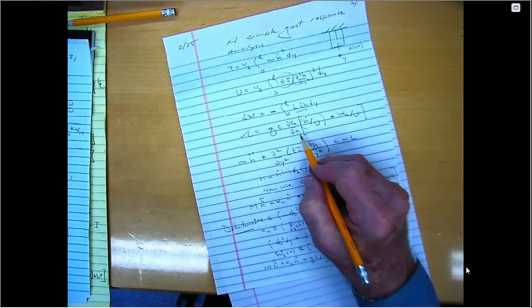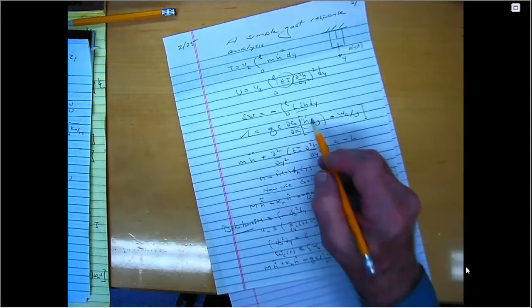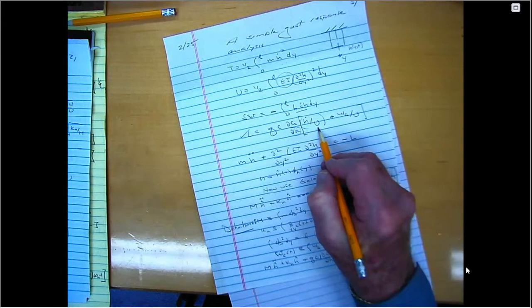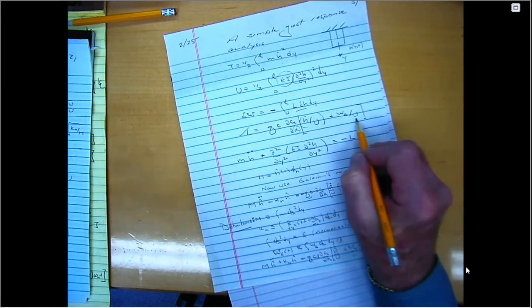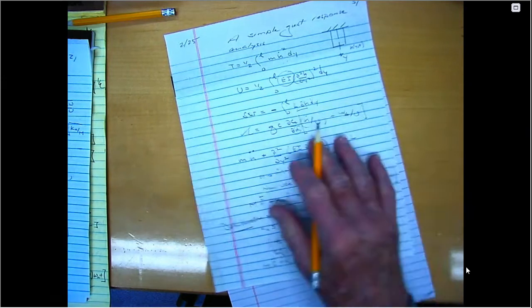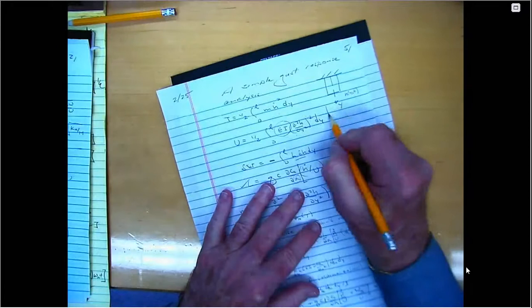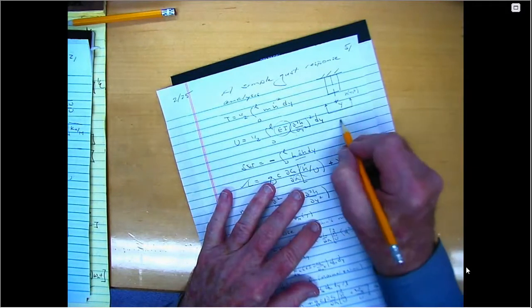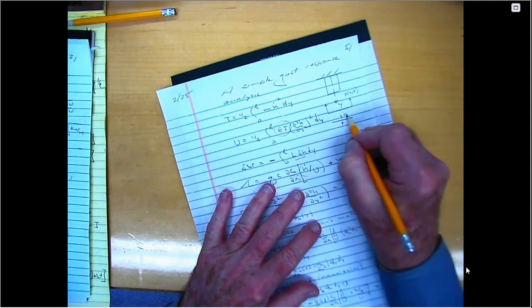times the effective angle of attack, but this is really no longer a twist per se. We're thinking of an effective angle of attack as the velocity of the wing divided by the free stream velocity, plus the velocity of the gust, because we're doing gust analysis, divided by the free stream velocity. So if I look edge on to this wing, here's the edge. I'm thinking of this thing moving up and down with h dot.